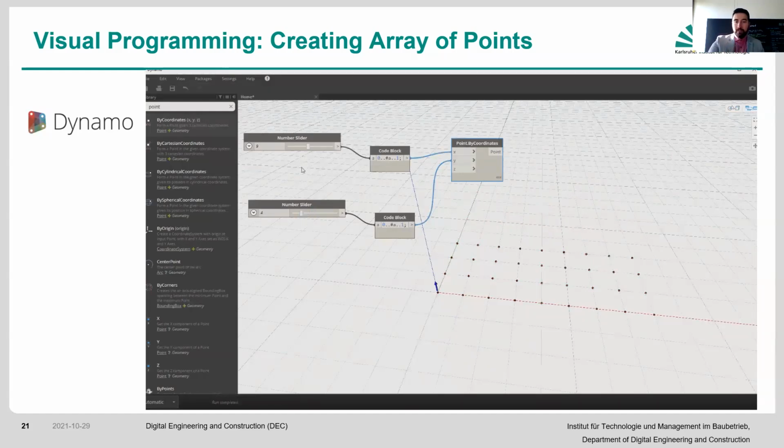And this is, for instance, because we haven't specified Z, so Z is going to be 0. If we do specify Z and add that as well, then it's going to be a box of grids, especially if we do the cross product. Okay, so you have quite a bit of options here. Now, the good thing is, for your Z, you might want to put some sort of function there. And it would basically create surfaces, like a perfect function with the mesh of your XY that you have there. So you might say it needs to be some sort of quadratic function. Then it will show you, let's say, half a circle or an ellipsoid. And then you would be able to get that particular surface from it.